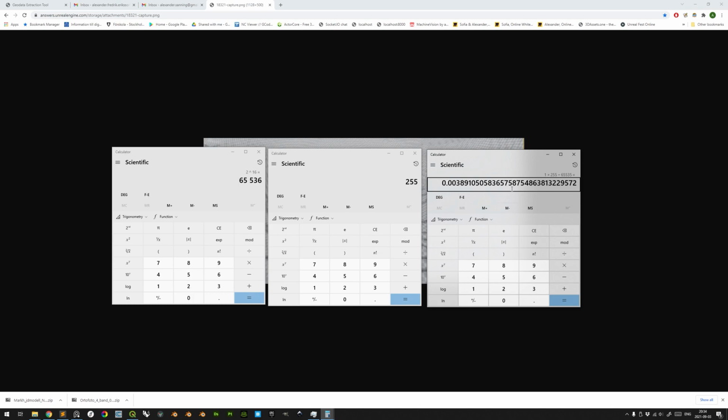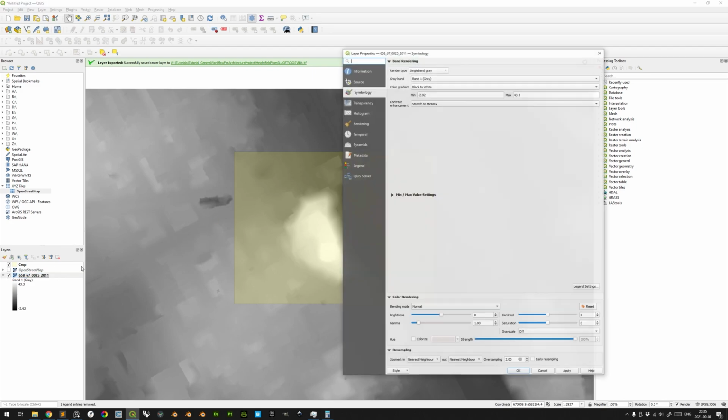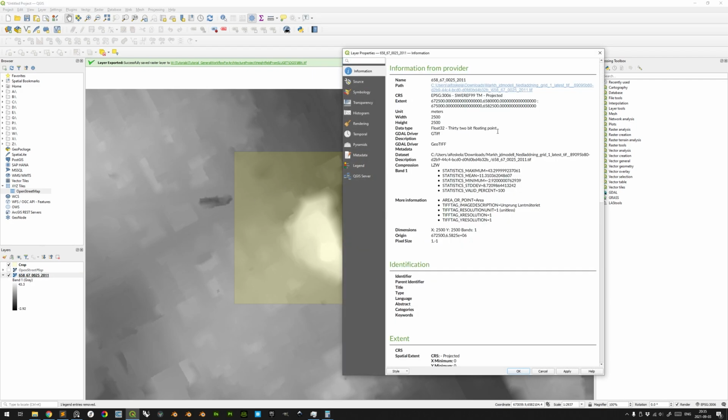A landscape with a larger height range than 255 meters will see the increments increase, and one with a smaller range will see the steppings diminish even further. But in most cases, if the increments are in the millimeters or in centimeters, they are not discernible to the eye. To make sure that you're getting the 16-bit data, let us convert the imported raster height data from a 32-bit, as can be shown here, which Rhino's Heightfield command does not support, to 16-bit.